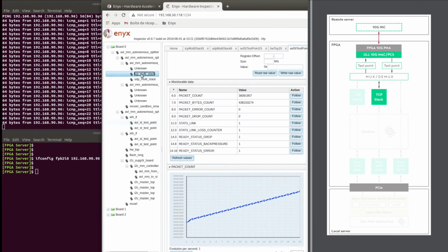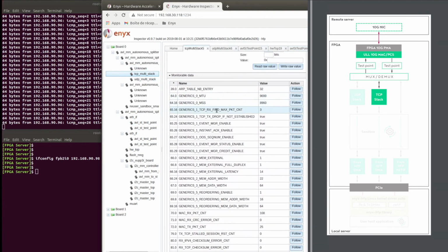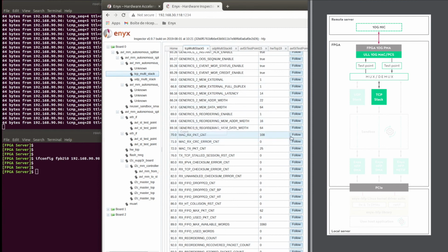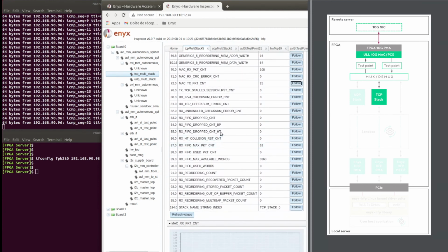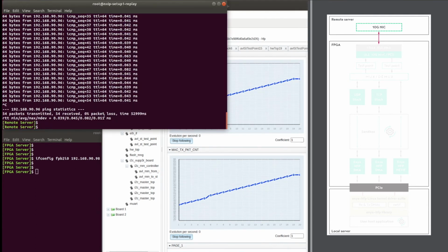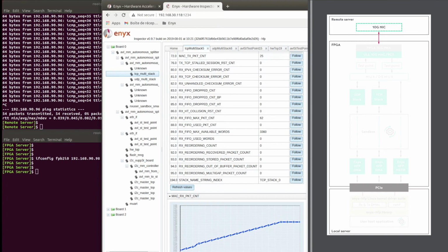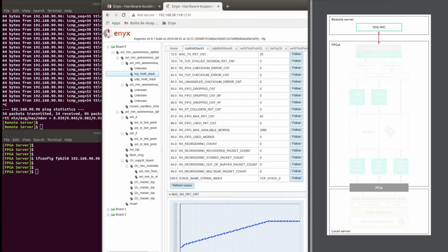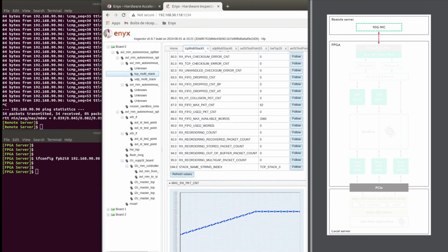We can see the pings once again, and the packets going through the corresponding physical interface, which is the same as the netif on this design. However, now the pings are targeting the TCP stack, and therefore can be seen in the TCP core. Here we can see the packets in the TCP stack going in and out.